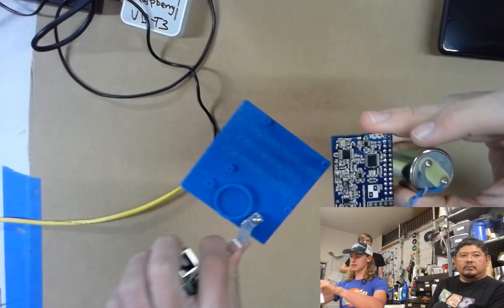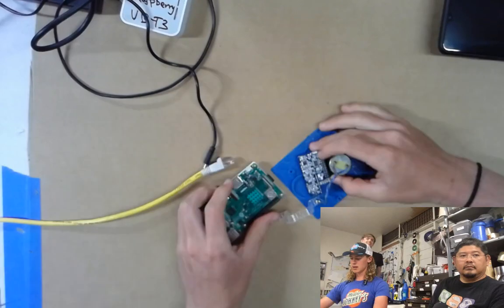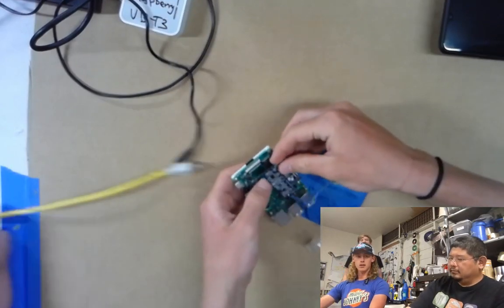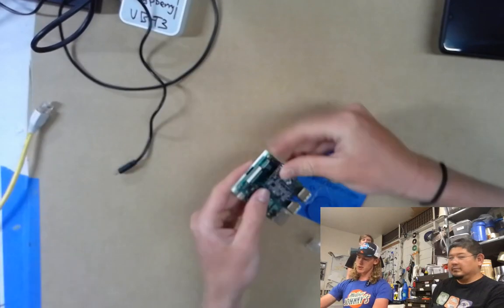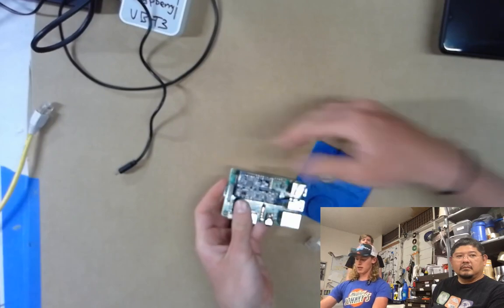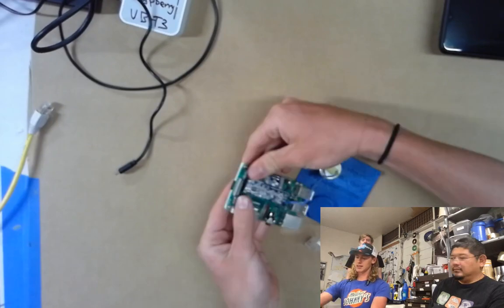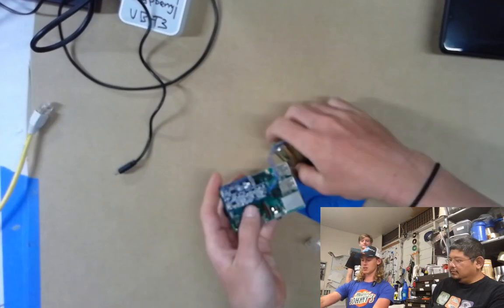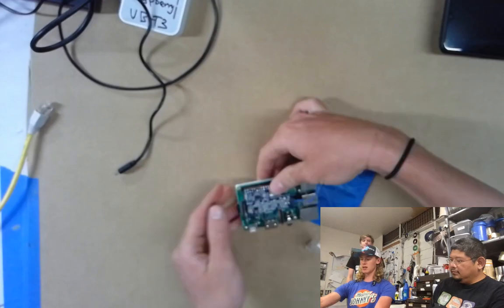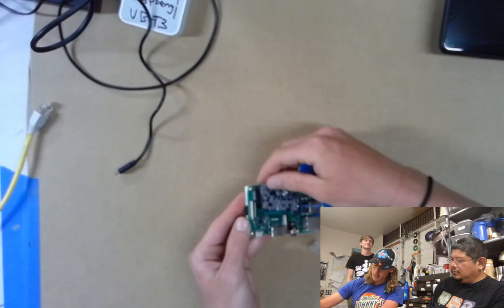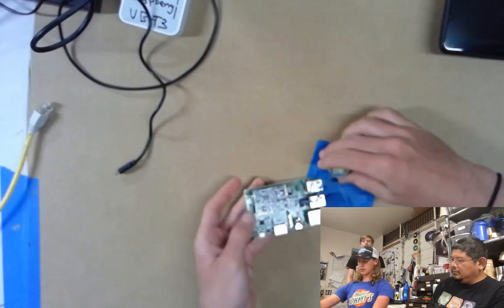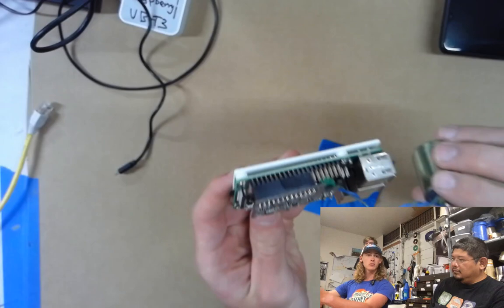this platform. So to start connecting it, you could first put the digitizer on top of the Shake by connecting it to the GPIO pins. And it doesn't connect to all the GPIO pins, just the ones on the farthest side from the USB ports and such. So that should be how it looks.